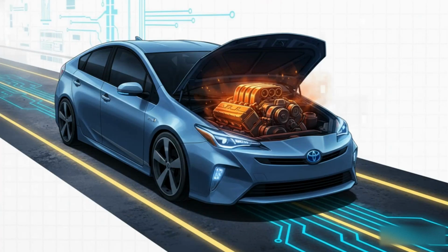And hey, while we're talking about speed, we have to give a shout out to another hero, BiCMOS. This is a cool hybrid technology. It uses standard, low-power CMOS for all the internal logic, but for that final output stage, the part that has to shout signals to other chips across long wires, it uses powerful bipolar transistors. These are totally different devices that are just fantastic at driving huge currents. They're the muscle you bring in for the heavy lifting jobs.